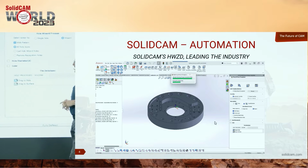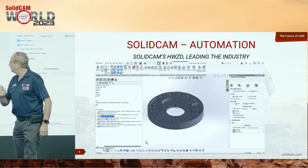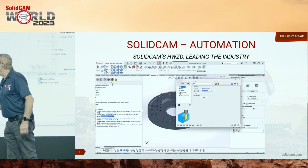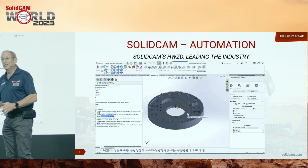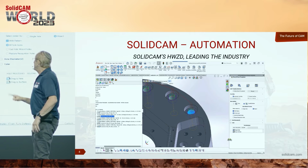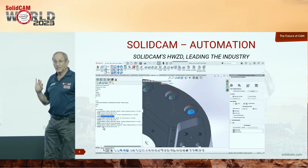Let's take a look first at the through hole that we've done with the drill. Remember, it's a 17 millimeter physical hole. However, the tool itself is 17.1. That means I used the modified information about it. And you can see also again that the actual hole is 17 millimeters.